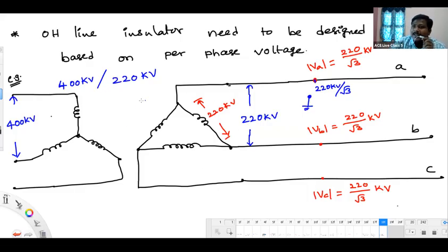Now tell me please. Irrespective of this transformer connection, whether it is a star connection or delta connection, doesn't matter to me. I will treat this transformer simply as a black box. Whatever outgoing lines we have, and we know the line to line voltage, each conductor will operate at a voltage of line to line voltage by root 3, irrespective of transformer winding connection. Is it a correct statement or not?